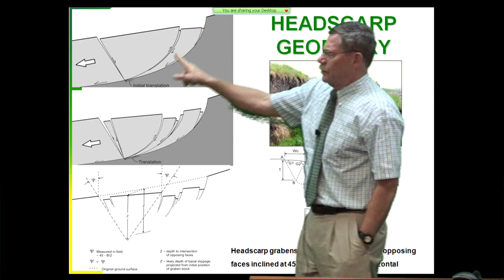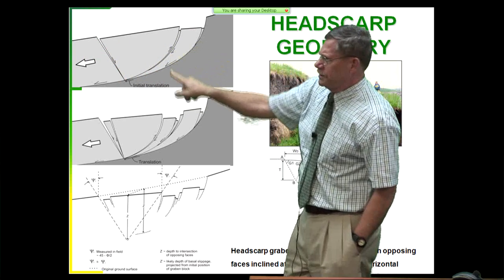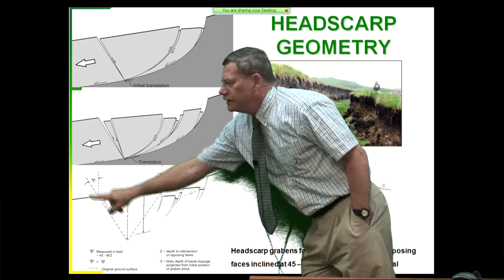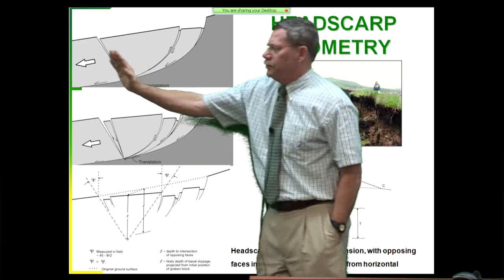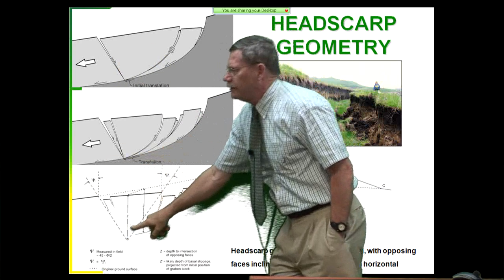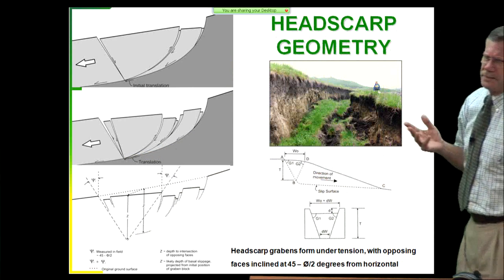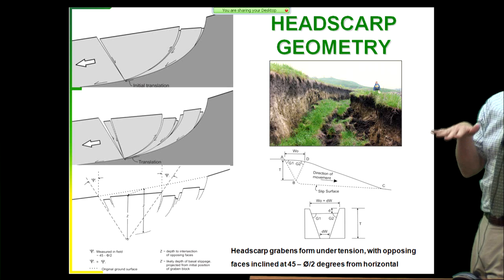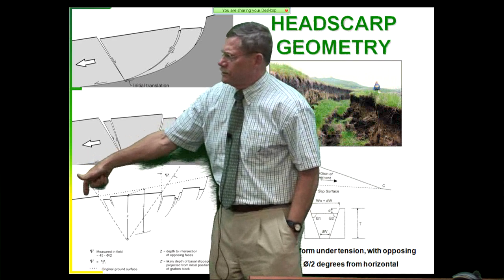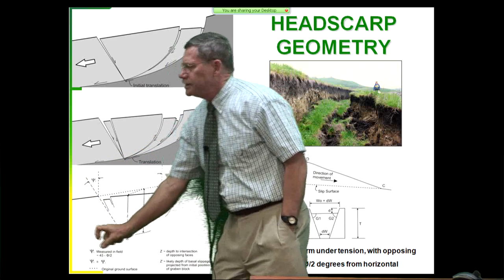When the slides get a little more complicated, this block mass starts moving, and you have more than one wedge in here, typically you'll see something like this, then our construction gets a little more complicated. We have to put this back up to where it was when it started, right there, and then come down to figure out the depth of sliding. But when I've applied these graphical methods, I'm always within just a foot or two of guessing where the slide plane is. And I'd like to know where the slide plane is, so when I go in to do my testing right here, I come out with the slide plane in my tubes down here.